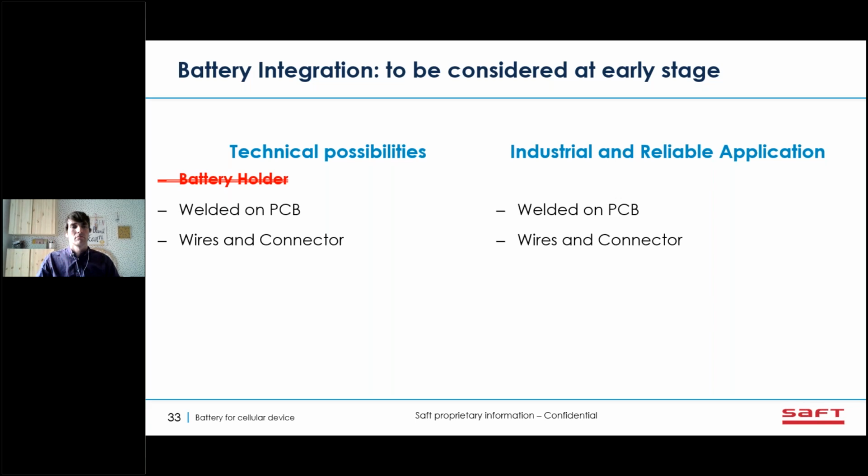Clearly, my recommendation is to avoid any kind of battery holder for industrial and reliable applications. A battery holder is a connecting system for consumer applications with alkaline cells. If you apply it with lithium batteries, lithium cells, it will generate micro-corrosion at the contact.